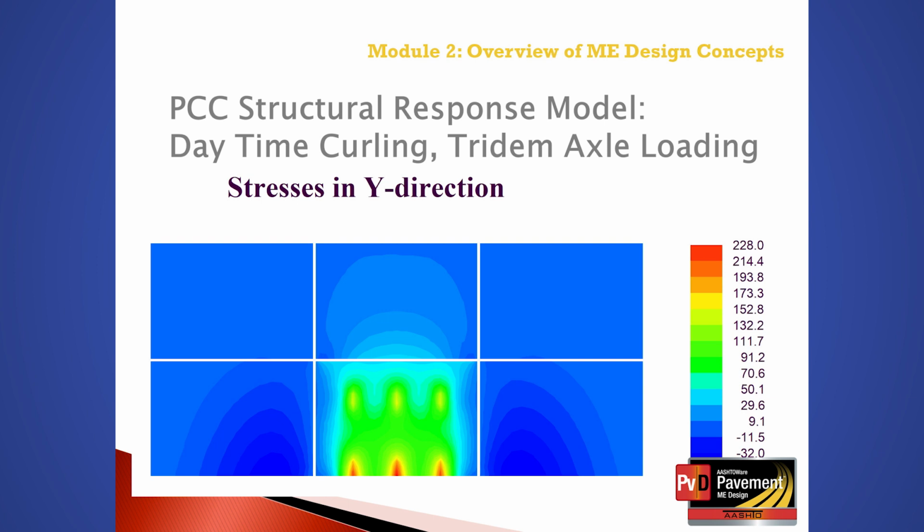In the previous example, the highest stress was only under the center axle of the tridem axle simulation, but with daytime curling, now the higher tensile stresses occur under each axle load of the tridem axle simulation as shown on the screen.